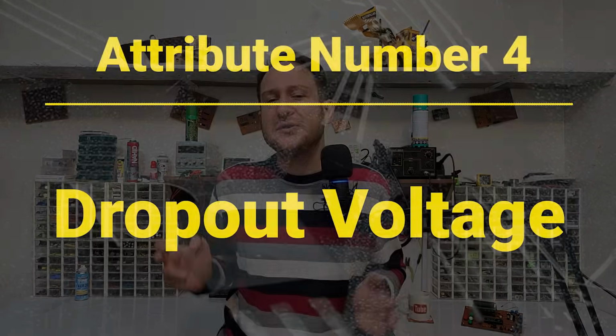Anyway, here you may ask, if decreasing the input voltage makes the regulator more efficient, can we bring the input voltage as close as possible to the output voltage? This question will lead us to the next attribute, attribute number 4, dropout voltage. Dropout voltage is the minimum difference between the input and output voltages needed for the regulator to function properly.